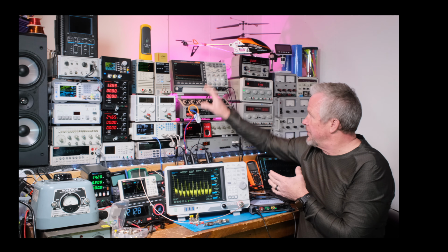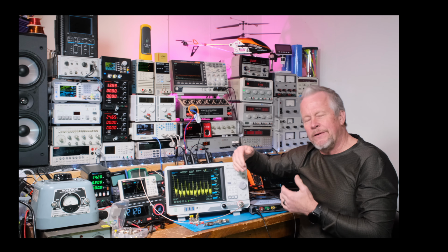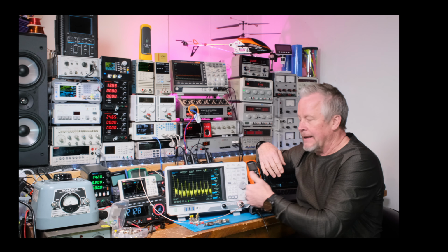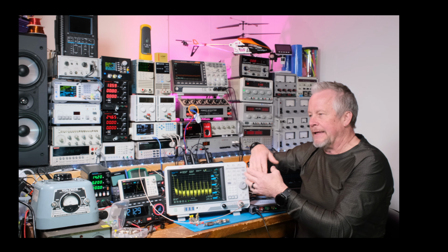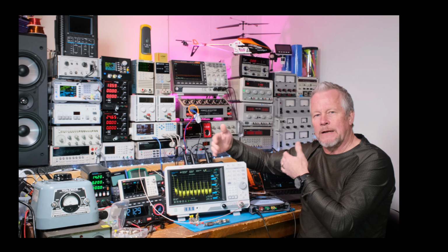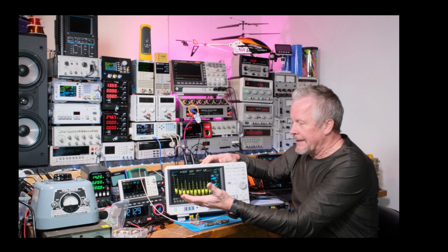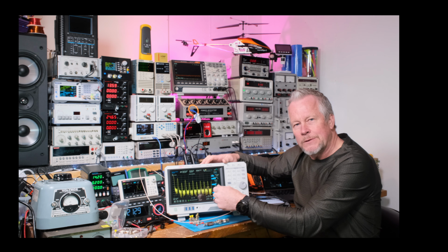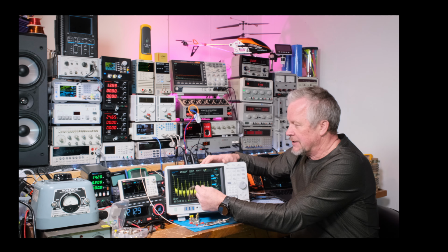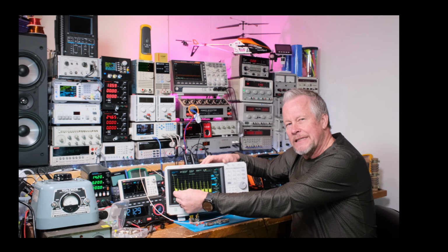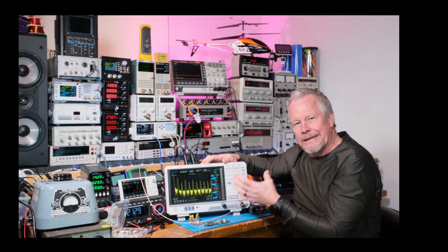So that's why they call this one a spectrum, because it looks and feels like a spectrum analyzer, even though it's still scanning like an oscilloscope, taking all that math, doing an FFT on it, and then allowing you to set it up like a spectrum analyzer. A real spectrum analyzer is different because it's kind of like a radio with somebody tuning in frequencies all the way across. It has this little bandwidth filter that you scan across and you pick up different frequencies. So that's a little bit different. Now, it doesn't really do it that way, but that's the way you kind of think of it.